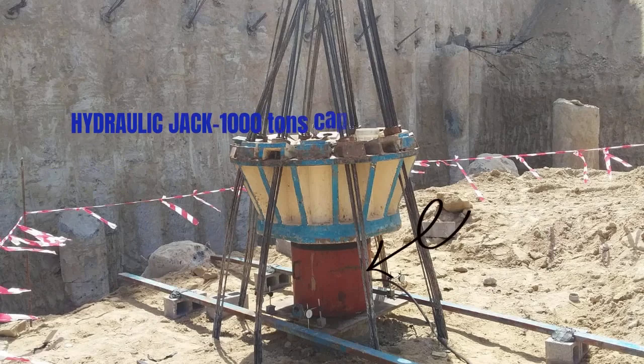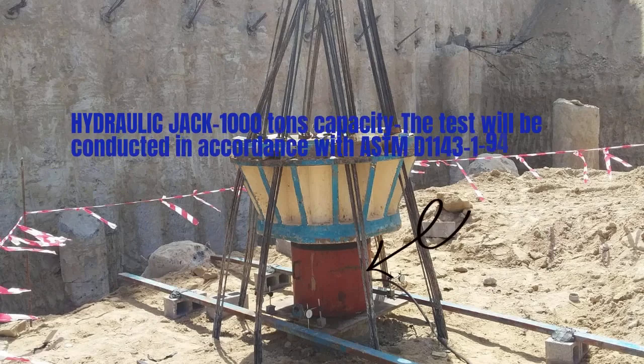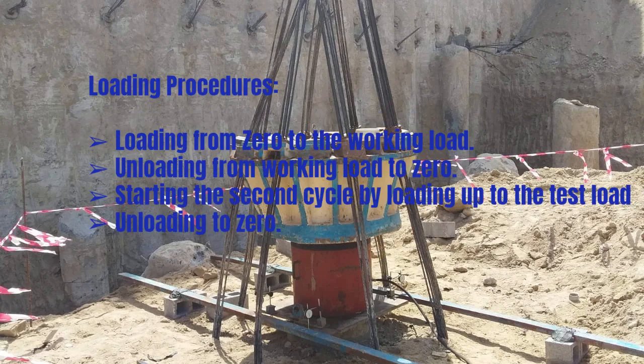The load will be applied by a suitable number of hydraulic jacks of 1000 tons capacity. The hydraulic pressure is recorded with a calibrated pressure gauge. The test will be conducted in accordance with ASTM D1143. Loading procedure: loading from 0 to working load, unloading from working load to 0, starting the second cycle by loading up to the test load, then unloading to 0.